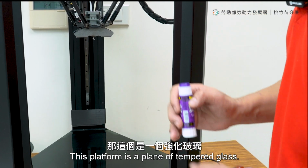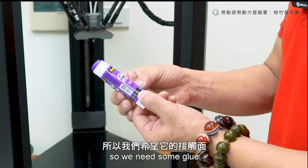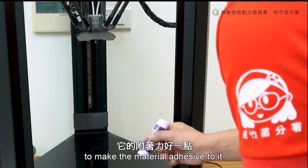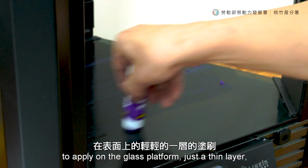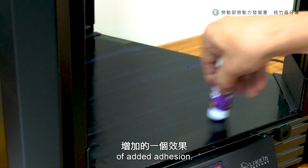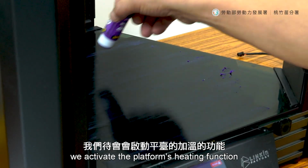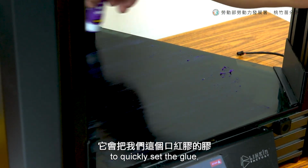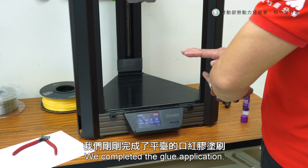This platform is a plane of tempered glass. It's smooth, so we need some glue to make the material adhesive. We use a glue stick to apply a thin layer on the glass platform for added adhesion. After applying the glue, we activate the platform's heating function to quickly set the glue, making it congeal. Okay, we complete the glue application.